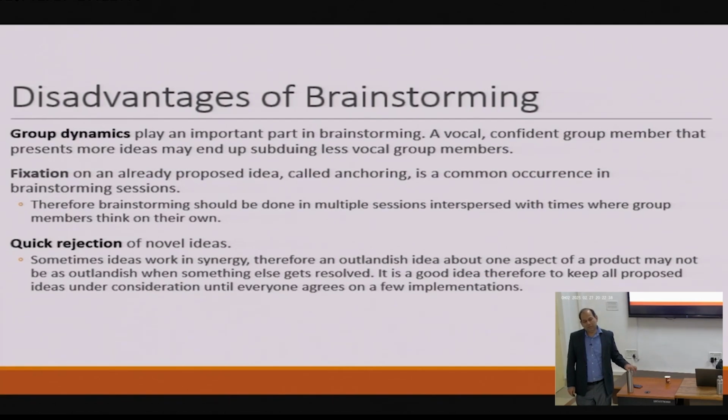But then you could say, you know what? I know that a square wheel car will have predictable motions, right? Every 4 times at 90 degrees separation, the car will actually jump up. Then I can do active suspension to cancel that. Then you say, you know what? Forget the square wheels. Now we have an idea. We should have active suspension.